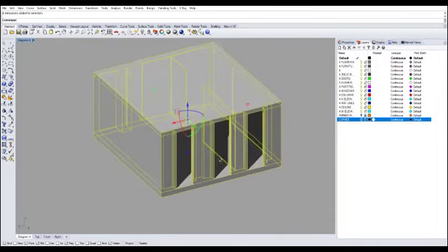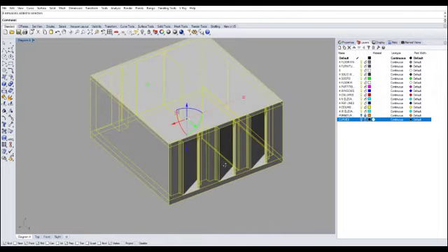Again, be very delicate and slow about this, because when you copy and paste an object in Rhino, it places it exactly identical and in the same place as where it was before. So it's going to be very difficult for you to extrapolate out if you do not follow this step quickly and for the first time. So do it very carefully when you do it.